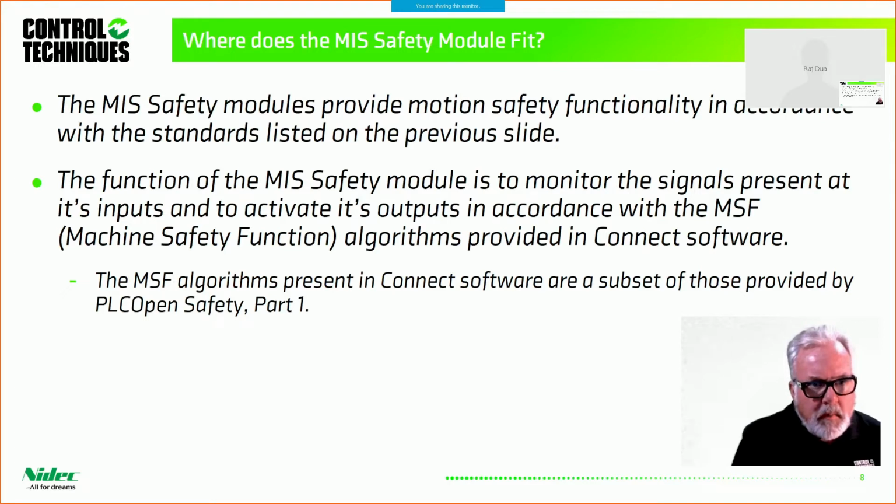So where does the safety module fit? Well, the safety modules provide motion safety functionality in association with the standards on the previous slide. The function of the safety module is to monitor the signals present at its inputs and activate its outputs in accordance with the machine safety function, MSF, algorithms provided in Connect software.